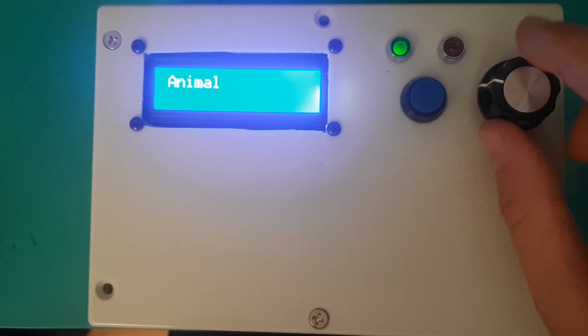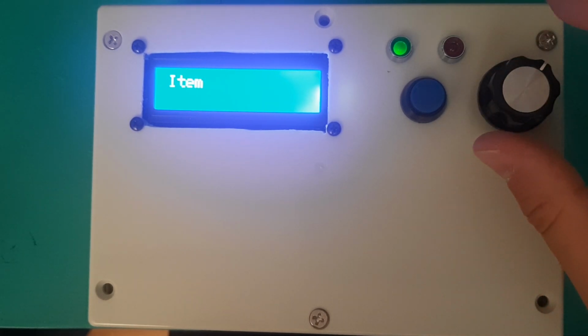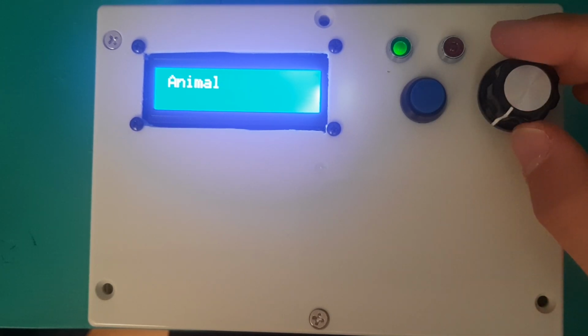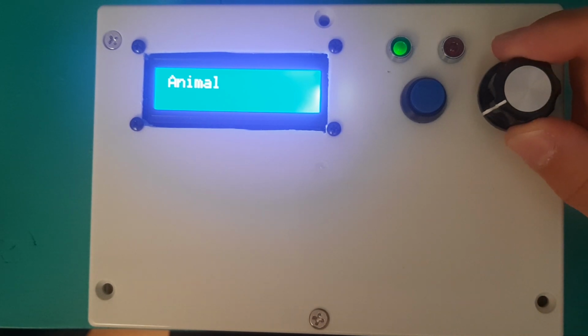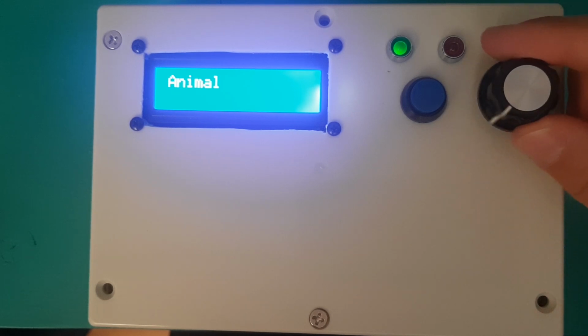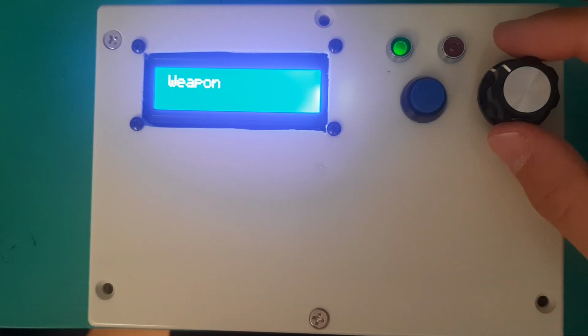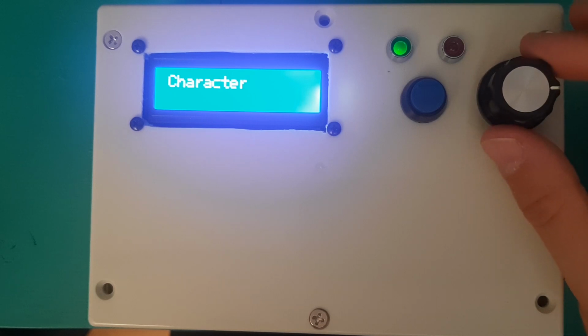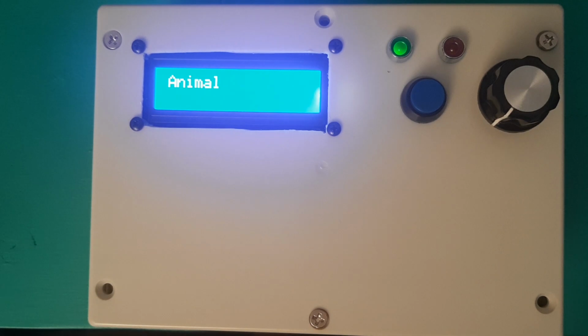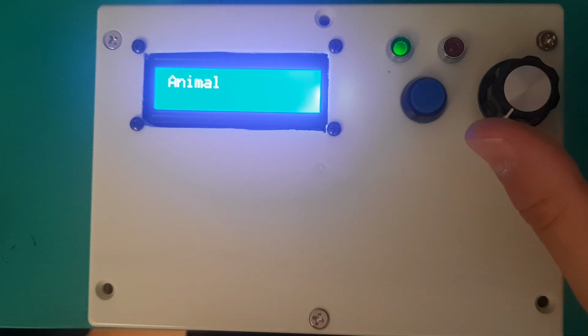And remember, if you're using a logarithmic potentiometer, you're going to have the same problem as me: at the beginning you have a lot of turn to do until you get to the second menu, and when you get to the end they are much closer one from another because the value of the potentiometer is exponential. So you're better with a linear potentiometer.